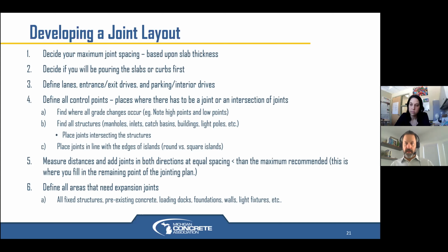But they will go ahead and put that longitudinal joint right back through that longitudinal repair area, creating roughly a 15-inch slab on either side of it. They don't put tie bars underneath that cut. They only put the tie bars into the existing slab on either side. But yes, they score that line back through that repair. So that would be a similar detail to what MDOT has, and we can provide that to folks that are interested.